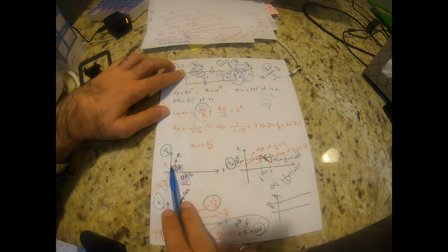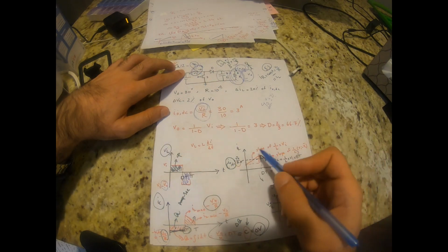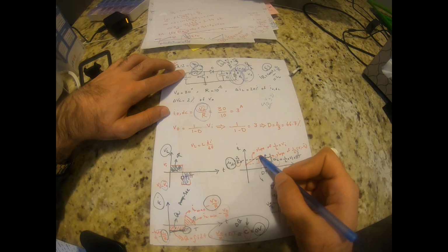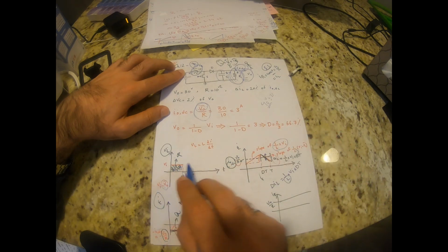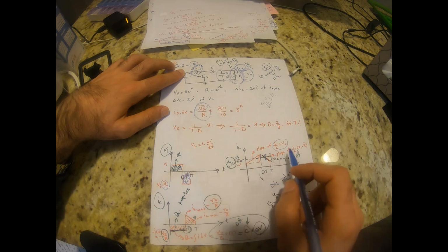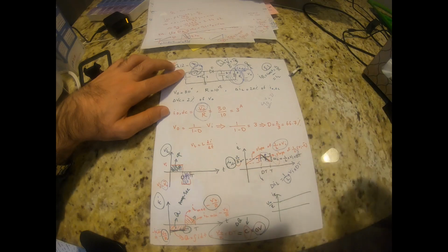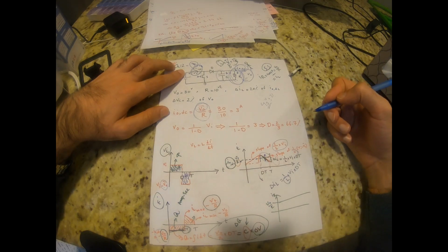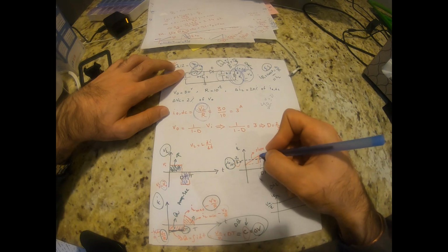When you apply constant voltage onto an inductor, its current is going to increase linearly with the slope of 1 over L times that voltage. So that's what we have here. And the same thing is going to happen for the discharging period. If we are in the steady state, you should end up at the same level, right? That means that this charging and discharging has to be the same.